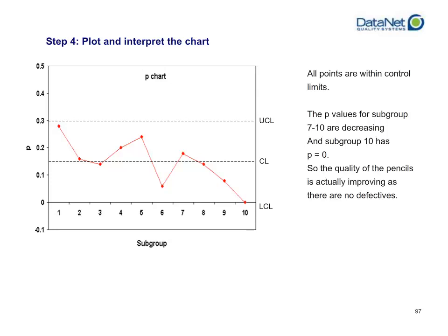That's not to say you can't have a process where it would actually be unusual to have no defects. That can occur. Hopefully you do have a process that is capable enough that it's not expected that you produce defects, but there are processes where that is in fact the case, and actually finding less than normal defects would be cause for alarm, to figure out if there were some abnormal circumstances, or an incorrect reading, or maybe even somebody fudging the data. So it's very important to look at even situations where things are behaving better than you would expect, because your ultimate goal is to find out: is your process stable, and is your process beginning to shift or change? Is there any non-random variation acting upon your process?